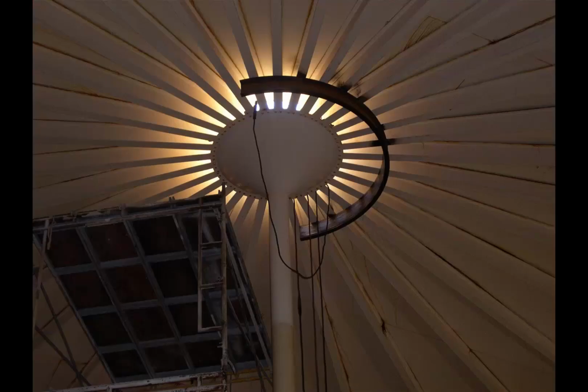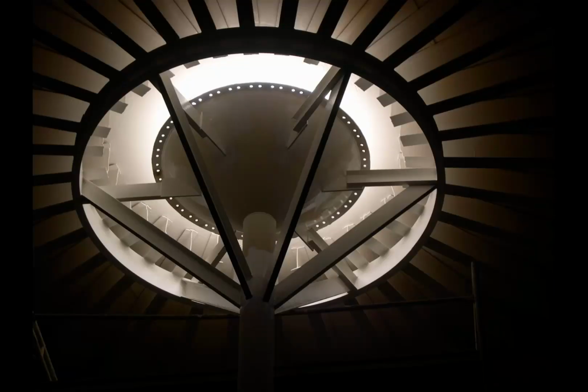So what we ended up doing was we had to take the reservoir out of service, and this is what's called a halo. So you can see that they were constructing just that, a kind of circular beam mechanism around that center column. Ultimately they brought beams down to support that halo, and then as you can see, all of the rafter beams that previously came to the dollar plate were cut off, so we cut it back to a portion where that corrosion was gone, and then the more solid portion of the rafters remained tied to that halo, so all that load was then transferred to the center column by the beams connecting the column to the halo itself.